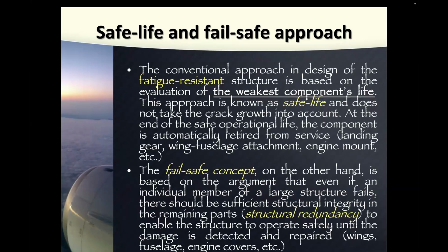But we have to follow the crack growth of that crack, the rate of growth, and eventually we have to do something: either replace that component with a spare part, or make some patches and then stop there. So we will see some of these efforts a little bit later.